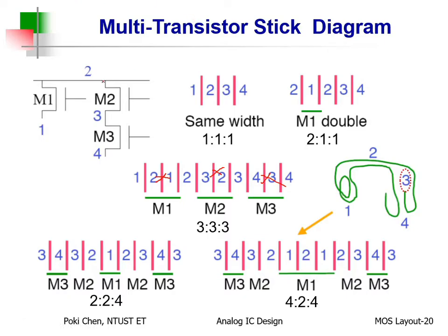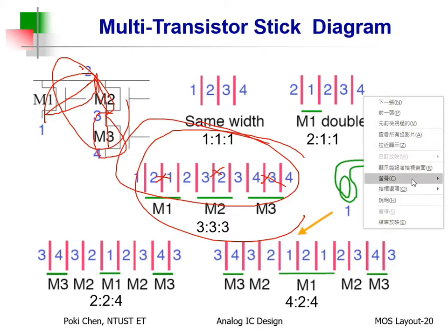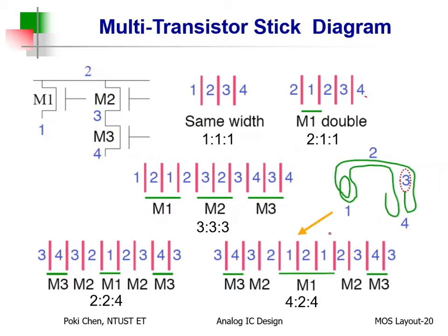With what I told you, 1, 1, 1, 2, 2, 2, 3, 3, 3, I promise you, even though they don't have a common centroid, their centroids are much closer than this. So the layout's centroids will be very close, although not overlapped, far better than that one. That's it. All right, you can do it by yourself. Piece of cake with one-stroke drawing.